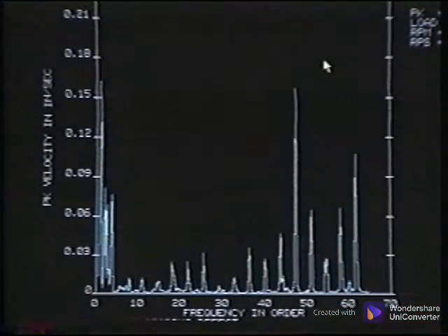First, let's consider several characteristics of outer race defects. This particular spectrum has a lot of high-frequency energy that is caused by the outer race of the bearing. Notice that these peaks are out of the high-frequency area of the spectrum. The primary or fundamental outer race frequency does not even appear.